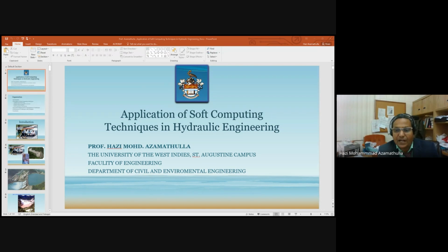This is Dhauliganga Dam spillway. For any project, as you are all aware, we have to do some model studies before execution. This is a 1 is to 70 geometrically similar model. You can see on the right hand side there is a chute. Chute flow here, with 3 gates operating. You can also see the upstream side there is a gutter here.